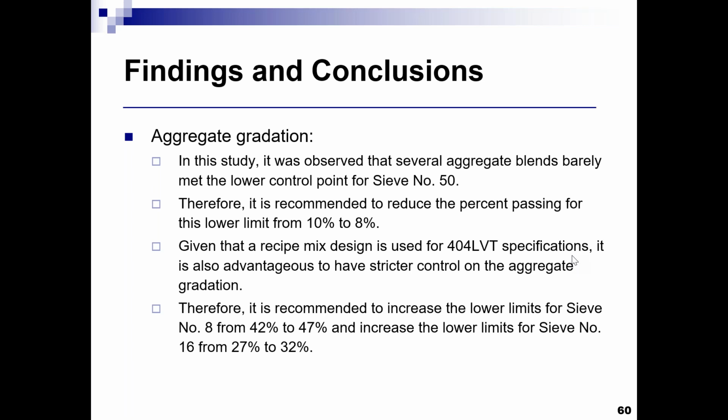However, if you are trying to use it in a residential area where that's not the case, or in a rural area where the roads don't have the best foundation, you're going to have extensive deformation in these pavements. You cannot really control the thickness to be 1 inch, so you may end up with a lower thickness than 1 inch at some locations. Then you may want to be a little bit careful when using that mix. So it really depends on where you're using the mix. I think it's a very good mix if it's used at the right location.